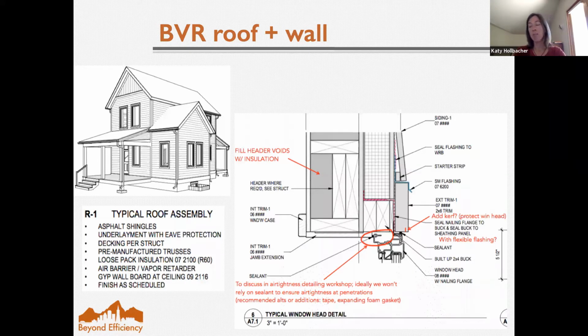Now, when it comes to something like radon, that's really, again, a function of just doing a great job under the slab and properly designing your radon system. I would say then to ensure that your radon system really is depressurizing that under slab or crawl space area, and keeping the radon out, having a balanced ventilation system that isn't actually competing with that radon system is going to make it that much more effective. So if I didn't answer that, please do chat again, and we can get into that more.